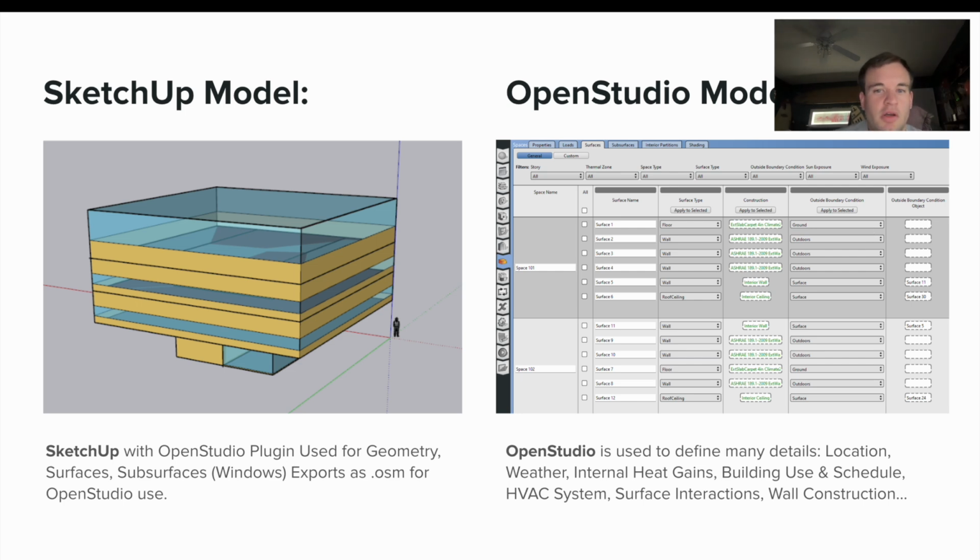The first part of creating the OpenStudio model, after I determined all those things using quantity takeoffs and understanding the zones, I went into SketchUp and used the plugin like we did for our class project. From that SketchUp model, I was able to define all these different glazing items. One note is I had trouble in SketchUp doing the pyramidal roof, so instead I made sure that the interior volume of air was still the same so that the load wouldn't be too different. And then I made all of those faces glass so that the solar irradiance wasn't too different.